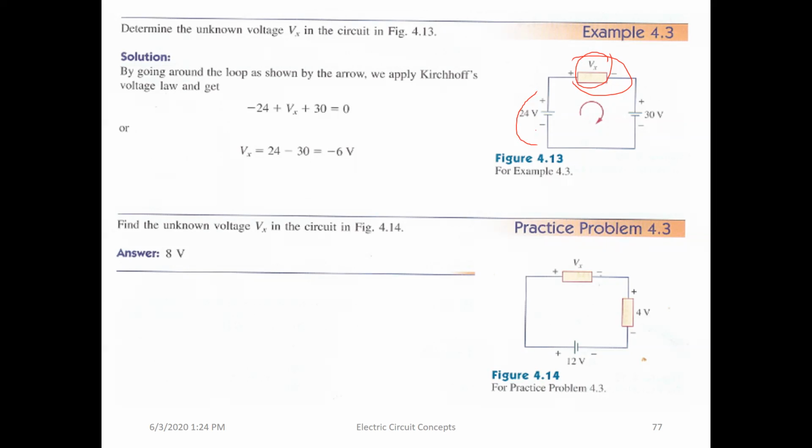So the first step: as I mentioned earlier, when you solve any problem, you write the formula of Ohm's law and the formulas for the power, I squared R, V squared over R. Now we need to add the formula of the KVL. This is new information we have to use from now on when we deal with a circuit that has more than one resistor or one element.